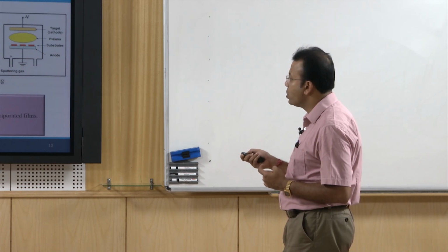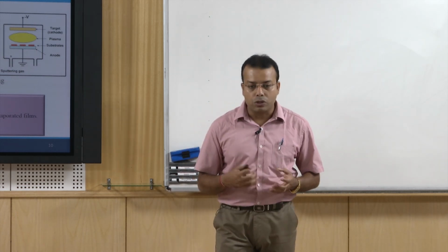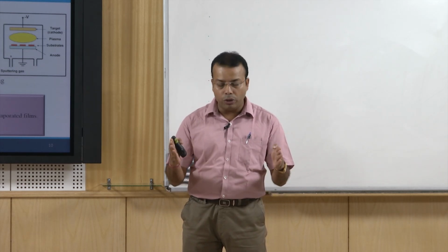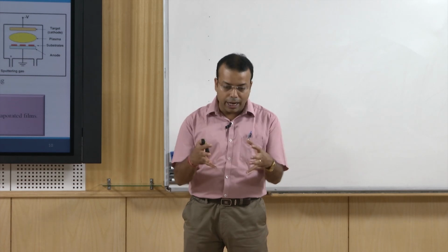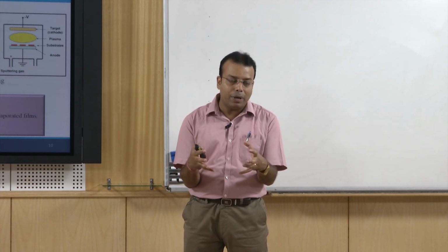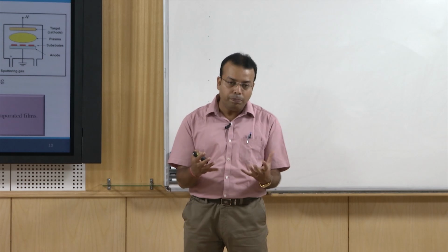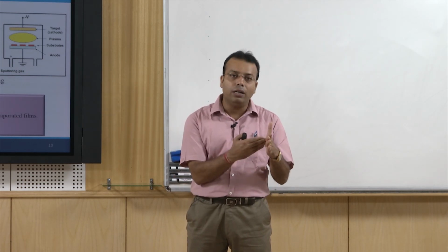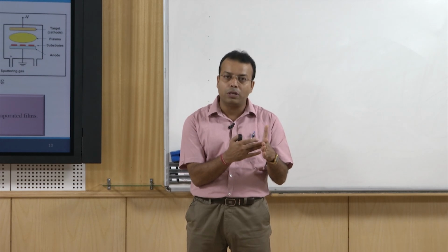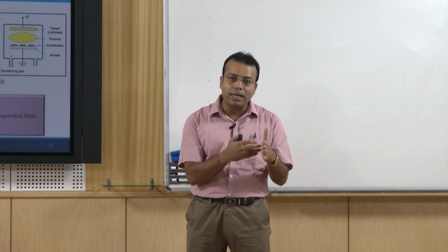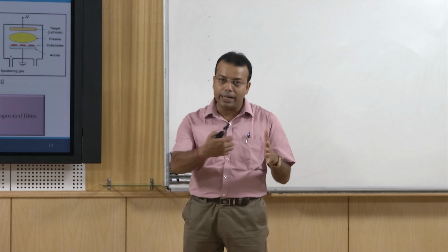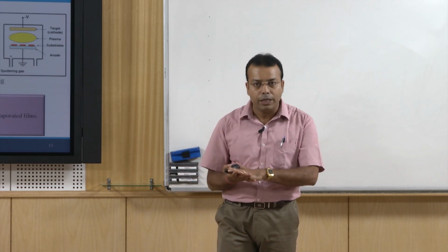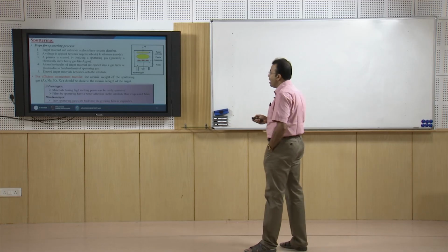Ejected target materials deposited onto the substrate itself. So, simply we are putting a potential difference between the cathode and anode, then we are injecting plasma, which comes directly from the argon gas. That plasma directly hits the target materials, or the source materials. Due to that, atoms or molecules come directly from the source materials and deposit onto the substrate materials. So, that is why it is called the sputtering technique.